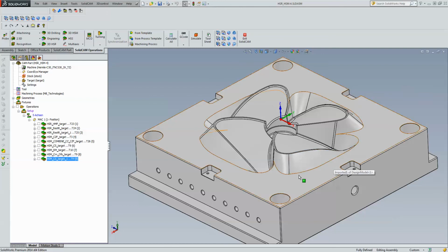Instead of doing what people tend to do, which is to take this entire area and do the whole thing with 3D constant step over, which is not necessarily the best way, the best way, as I showed you over here, was actually breaking it down using different types of technology. So the idea is to learn all the different types of technology that we have inside HSM itself, and for each area, break it down and do different operations for each particular area itself.